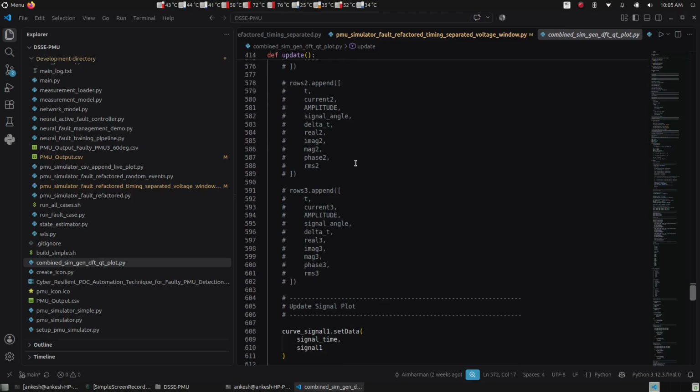This was our primary, what I can say, waveform generator without any fault. We did not induce any fault apart from the three standard waveforms which we added here. And why the three waveforms are not ideal waveforms, that is 120 degree separated waveforms, because usually what happens in the real scenario, we have different kind of loads which are constantly running in the supply, and these capacitive or inductive loads induce some kind of transients in the circuit.